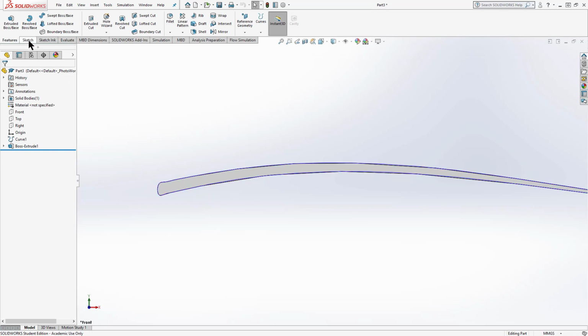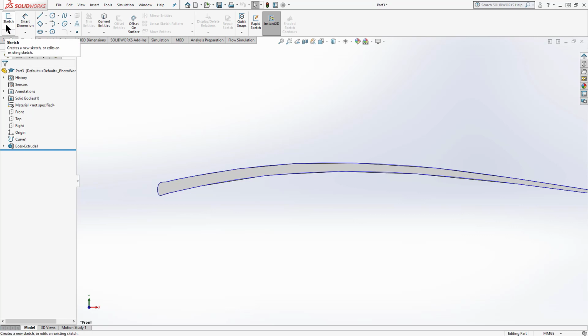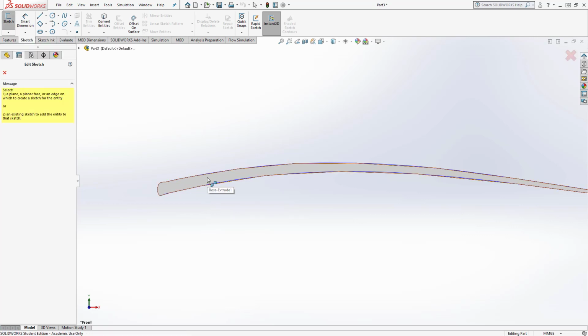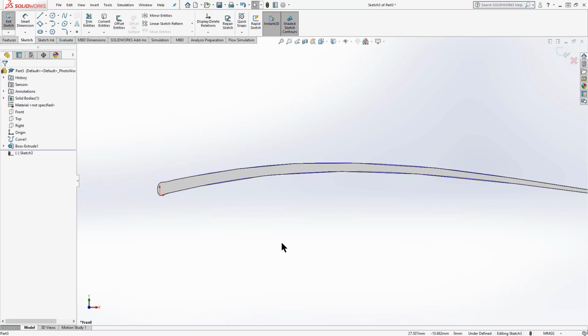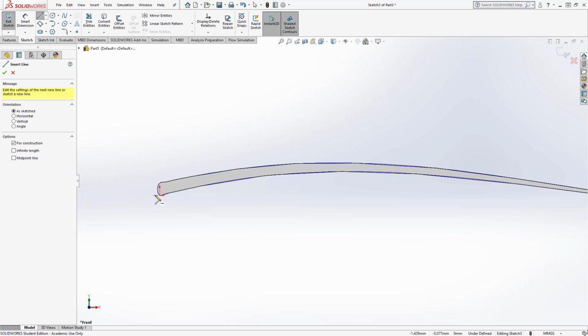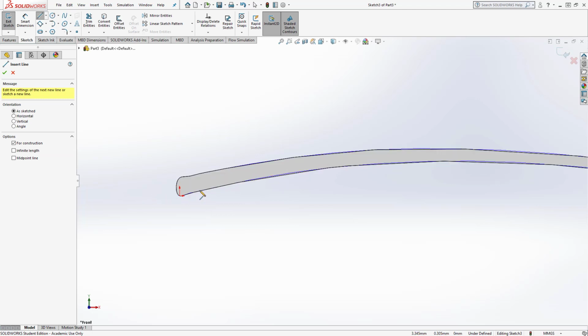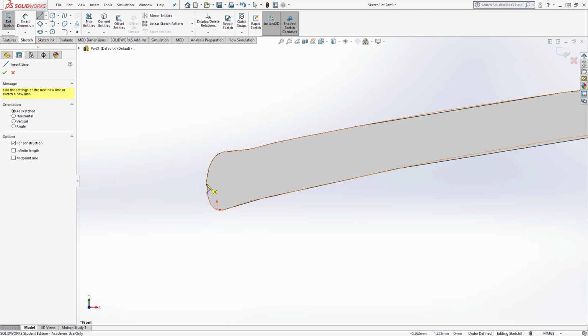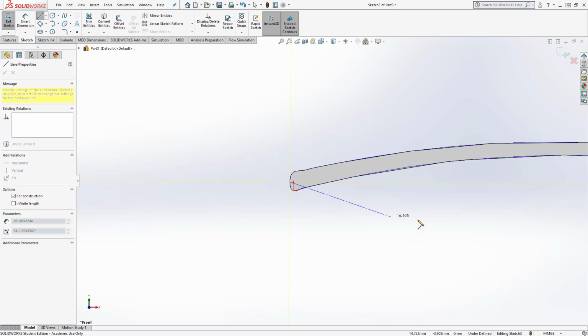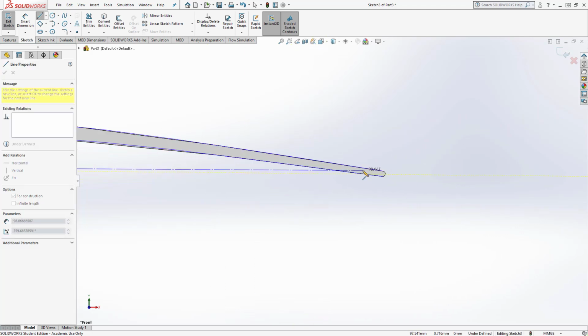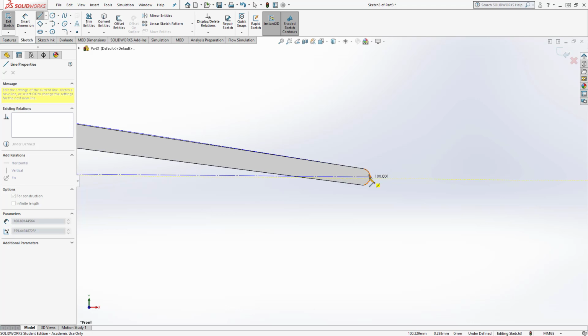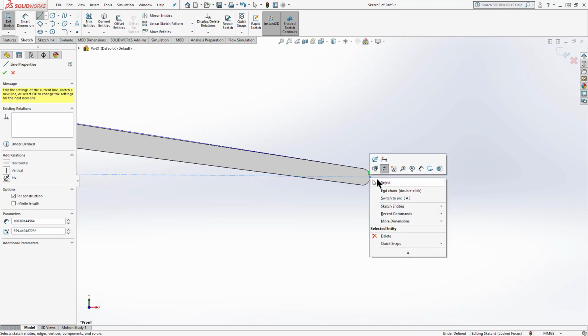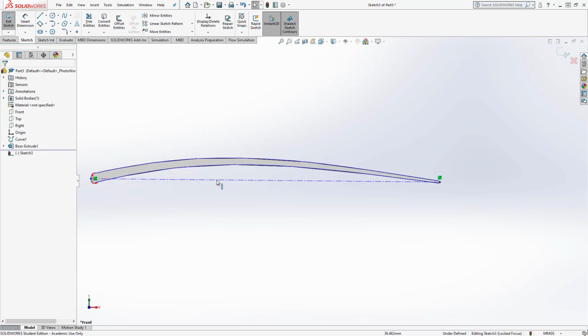So let's start a sketch tab, sketch button, choose the left hand side of your wing so that it faces out when you mount it. I'll then choose a center line, and I pretty much want to go from the midpoint here of this leading edge, and I'll choose that. Sometimes the origin is the midpoint, not always, to the midpoint of the trailing edge, and this is approximate. Doesn't need to be perfect. So there I've got a good chord line.